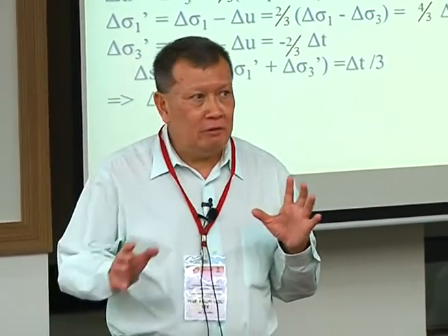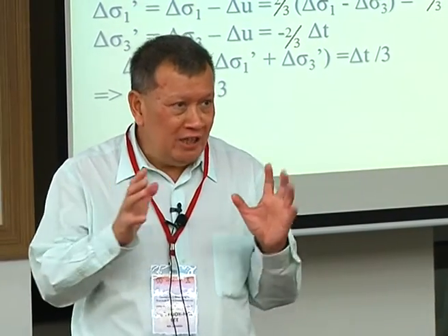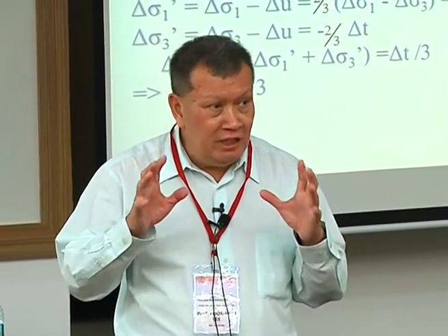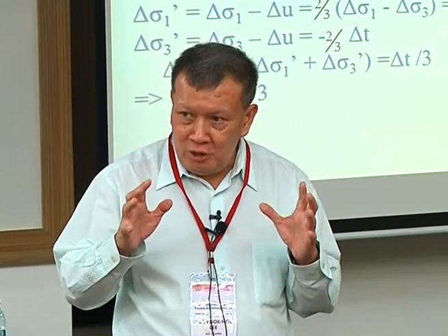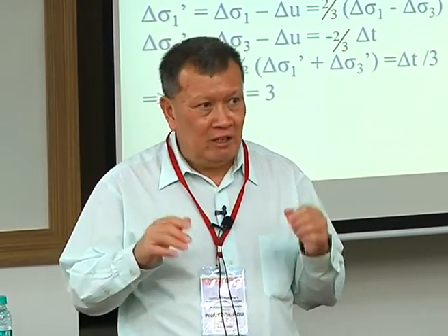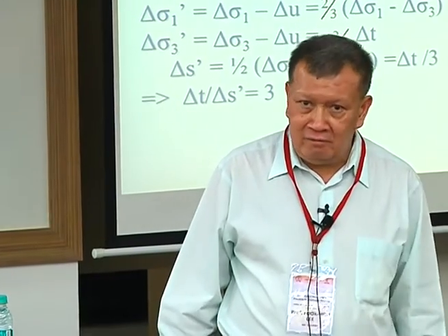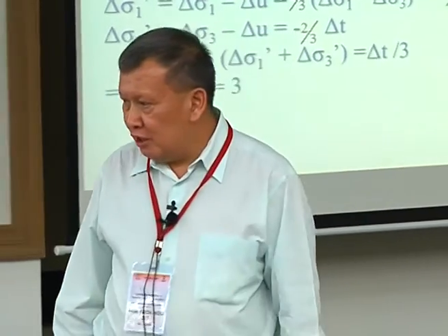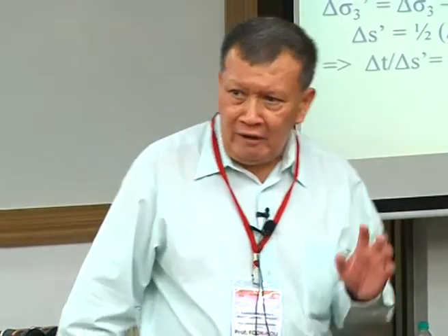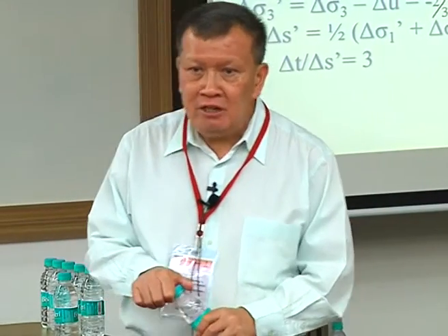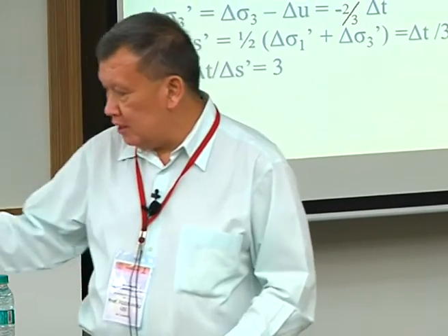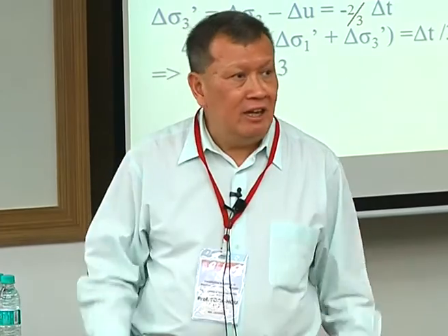And so, one of the usual tests of goodness of an undrained or drained triaxial test after consolidation is the degree of saturation. You want to ensure close to full saturation, so you check the B value, getting the soil lab to test for the B value. There are specifications in BS 1377 that the B value should be, I think, 0.96 or 0.95 or higher, something reasonably close to 1, before you can accept that set of test results. So B has a theoretical limit of 1.